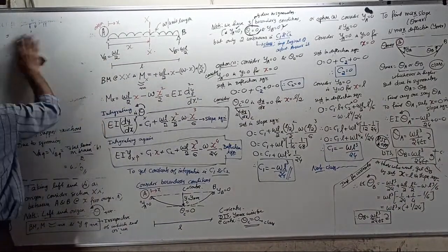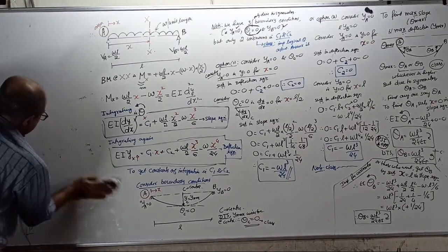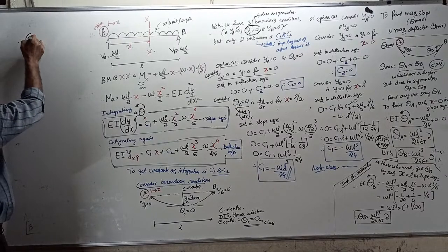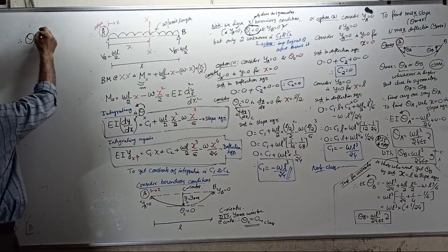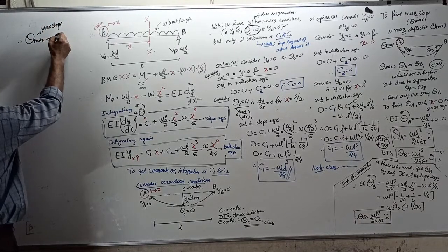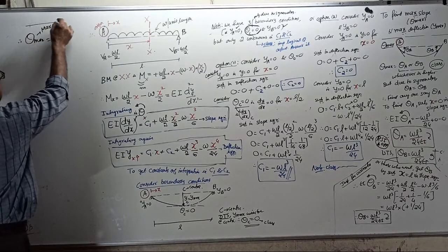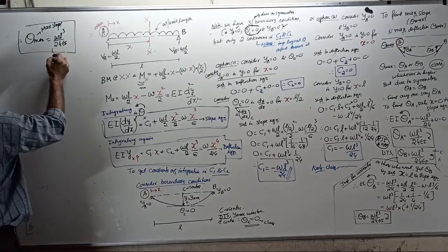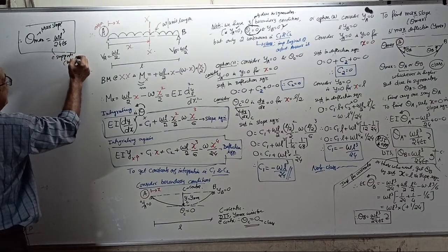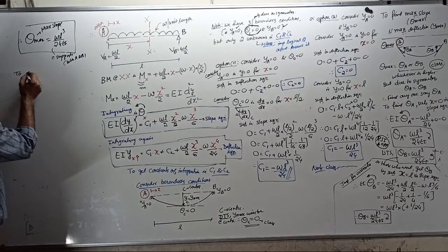Now see, we got theta A and we got theta B. Therefore theta max, that is the maximum slope for the beam, equals WL cube by 24 EI. That much in radians, at the supports, meaning both A and B.